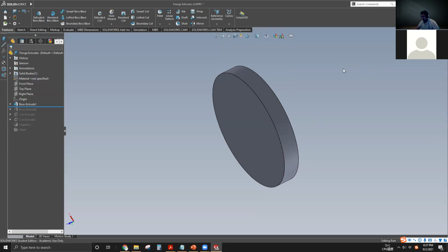Right? So, yep, you won't, because if you're trying to make a hub, you need to add material to it. Now, how can I add material to it? Either bolt it on or weld it, right? And that's really costly than just machine it.